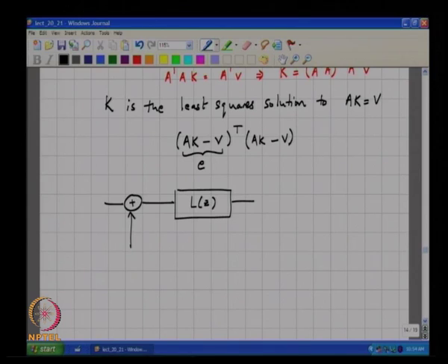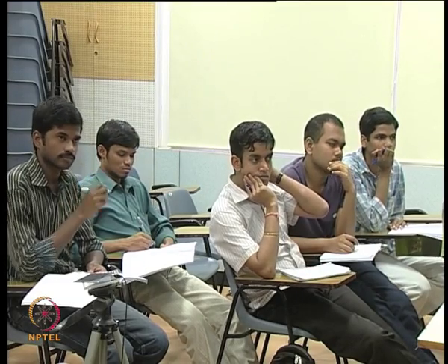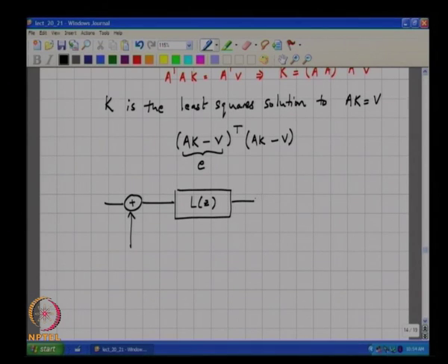So, this error, what is the mean of this error? It will be 0 mean, correct, because if the error is not 0 mean, I can always choose the coefficient such that the error is 0. Now I can represent the delta sigma loop, given that I have a linear approximation to the quantizer, by 2 loops,